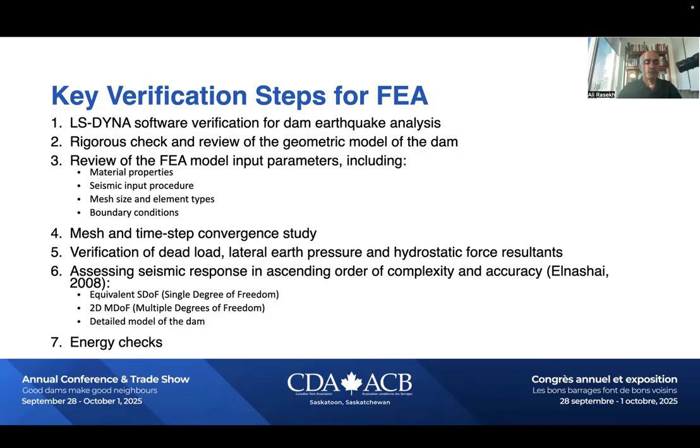That's very important. Mesh size, element size, boundary conditions, they are all reviewed. Mesh and time step convergence is a big part of our verification. And we also do check the dead load, lateral load, and hydrostatic load and their results.